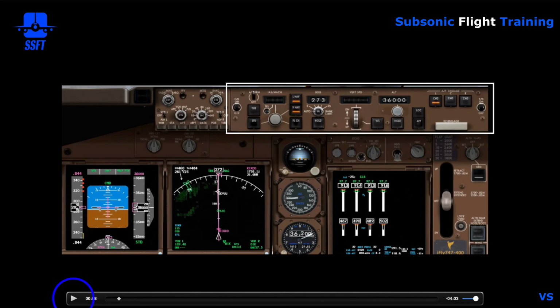Remember, we have to look at the FMAs, the flight mode annunciations, on the PFD, the primary flight display, in order to tell whether the modes are armed or engaged. In this case, you can see the autothrottle's in the speed mode, the roll mode is LNAV, and the pitch mode is VNAV path, telling us that we're engaged in all these modes. We can also see that the autopilot flight director engaged status tells us that an autopilot is in command.